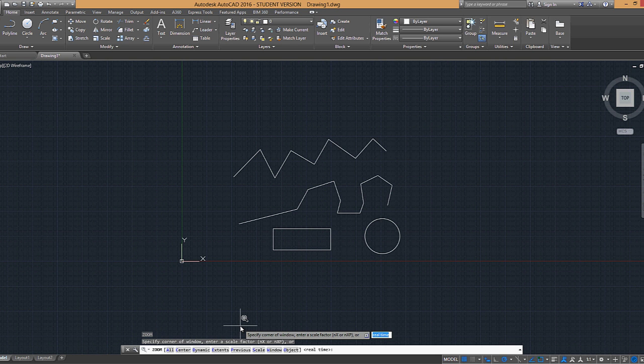One of the greatest assets for a beginner using AutoCAD is the command line, as I've mentioned. What's beneficial about the command line is that AutoCAD is essentially talking back to you and asking for further input when needed. Additionally, you'll note that most commands have subcommands. Those are additional commands that AutoCAD has associated with a tool, and we can see that with the zoom. So when we type in the zoom command, we can see the following subcommands: there's all, there's center, there's dynamic, there's extents, and so on. These are additional options with the zoom command.